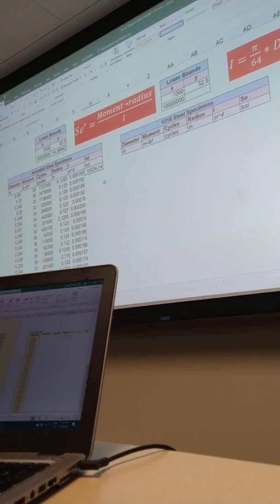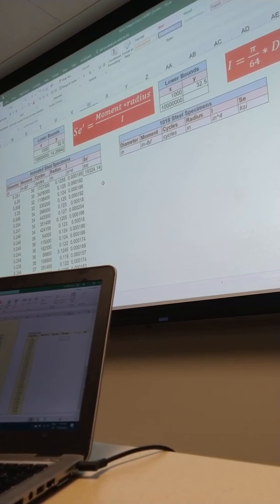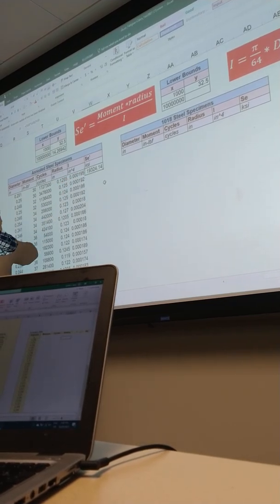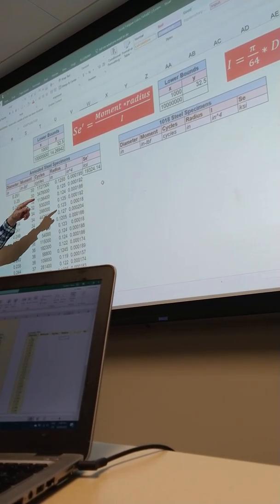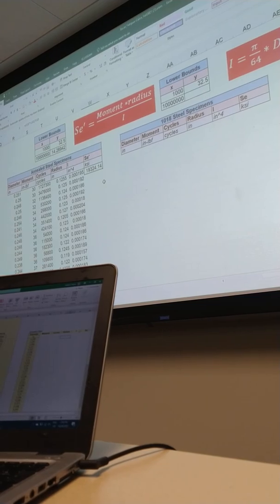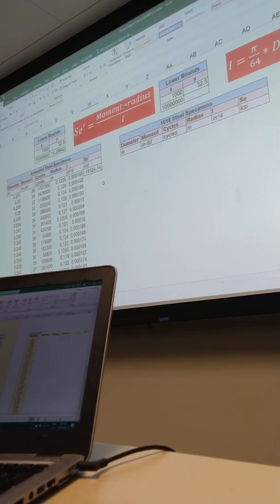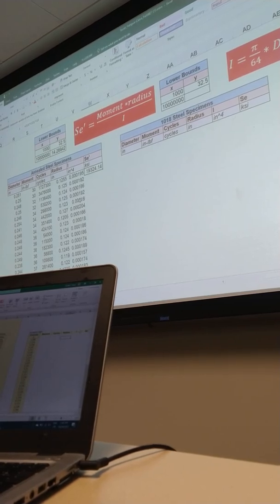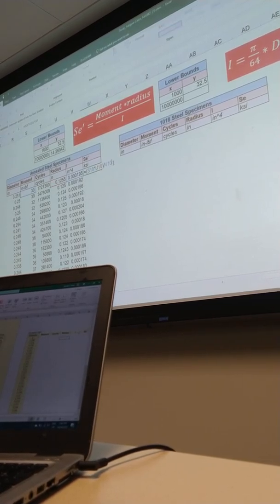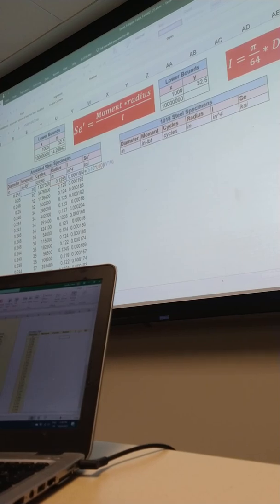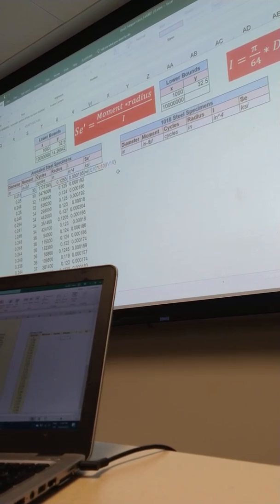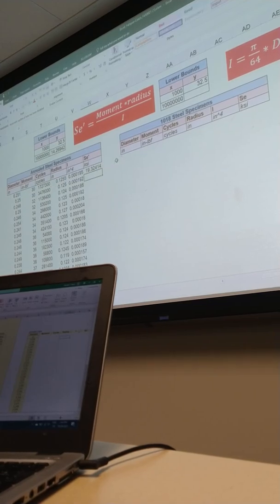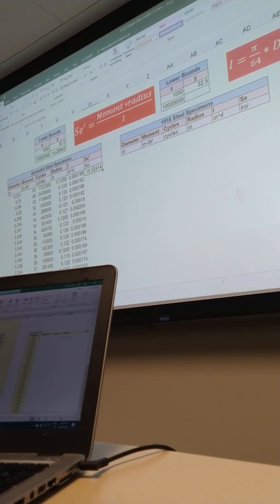However, you guys will notice the units here are KSI. And this is in PSI right now. So I need to get this to KSI, right? Because I calculate everything in pounds and inches, so it should be in PSI, pounds per square inch. So I need to get to KIPS. That's the easiest way to do that. Divide everything by 1,000. Cool. So now we got our stress range in KSI.